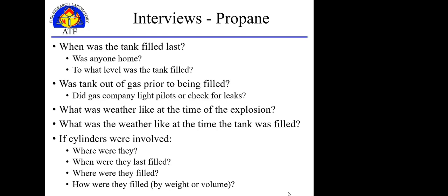So there are limitations on how full you can fill a propane cylinder. Again, if the cylinders were involved, where were they? When were they last filled? How were they filled? Where? They do volumetric or weight-based fills, and essentially it's only supposed to get filled up to 80% to leave that wiggle room for the gas to expand as it vaporizes due to temperature fluctuations.